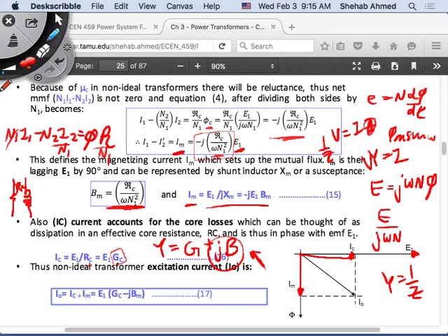Basically, I said that for the voltage that is produced, which is due to the flux linking both turns, to be there, I have to have flux flowing in the core. For flux to flow in the core, I actually need magnetizing current to be present, right? N1I1 minus N2I2 has to have a value. The difference between these has to have a value, and we call this difference between them magnetizing current. So it has to be there when the voltage is there.